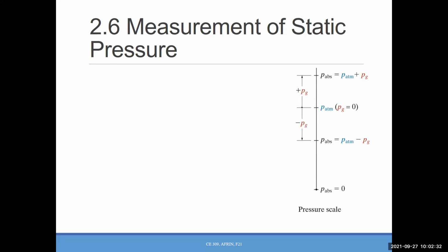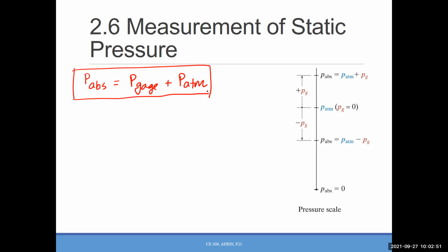From there, when we measure the pressure, that is the absolute one. And gauge one is what we measure with respect to what? The atmospheric pressure. So the relation between these is P gauge equals P absolute minus P atmospheric. We use that relation for different purposes.